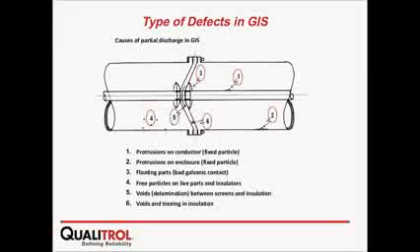We have voids in the insulation, which are, again, bubbles, and we have the epoxy insulator, and you can see here a bubble in the epoxy. Sometimes it can pass through the manufacturing process, a high voltage test, and a high voltage test after commissioning of the equipment, and it still didn't cut that bubble. It may not be a problem at the beginning, but eventually in the future it can increase and become a problem.